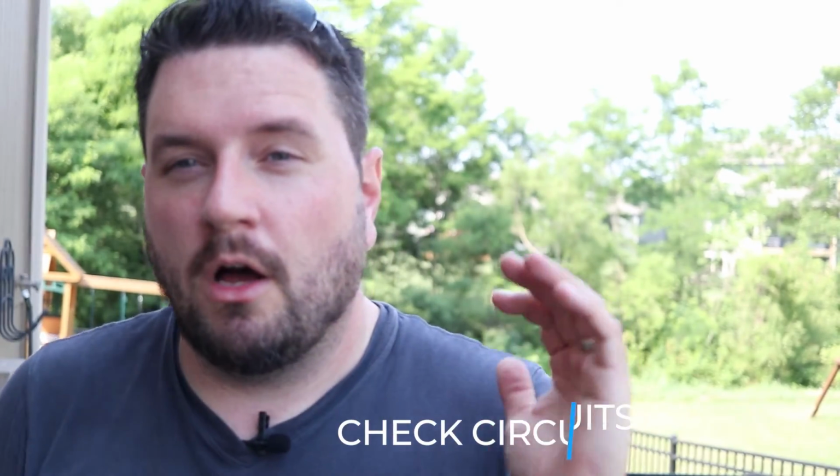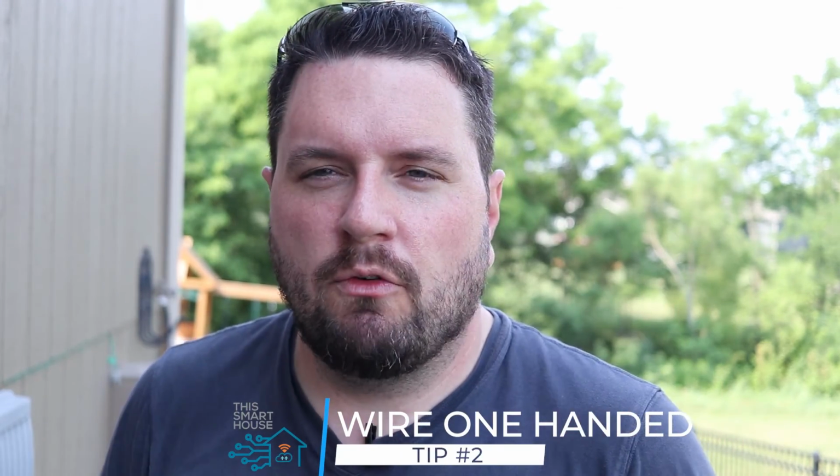All right, so a couple items for electrical safety that you need to make sure of. First, always make sure you test your circuits before you work on them. That's what we just did with the multimeter. You need to make sure 100% that there's no power in the system before you start working on it. The second thing is when you're doing any type of wiring, always use one hand to do the wiring. Try to avoid using two hands, so don't grab a screwdriver with one hand and then use your other hand to pull something. Try to always do your wiring with one hand, because if you were to complete the circuit and actually get hit with some voltage or current, it'll travel down one side of your body and hopefully avoid your critical organs like your heart.